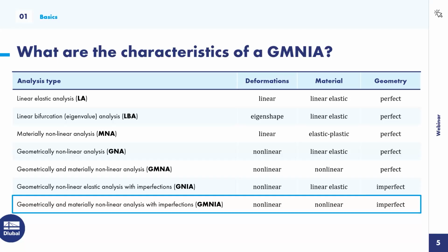Some rules for the application of a finite element method in this context are given in the Eurocode 3, part 1.5, Annex C. And this will be shortly replaced by a dedicated Eurocode that's dealing with finite element methods and its application for steel structures, and that will be bundled in the Eurocode 3.1.14 in the second generation of the Eurocode. And I will refer to this new code as well during this presentation.